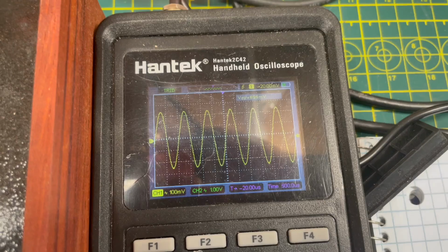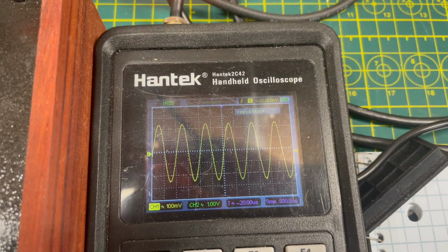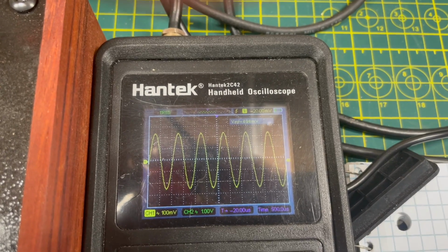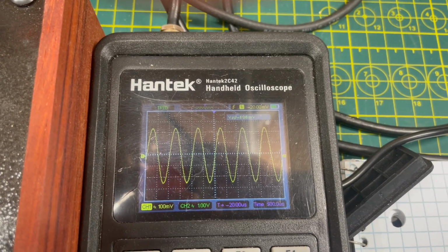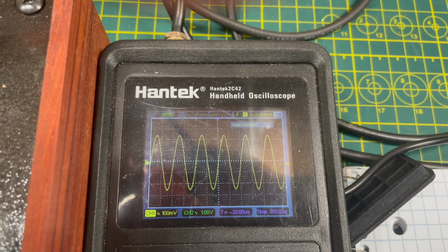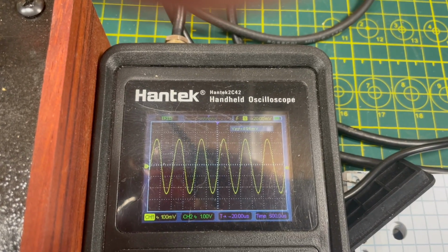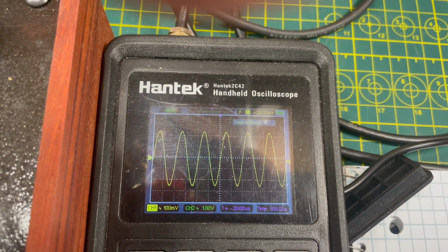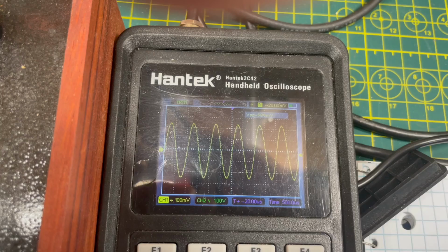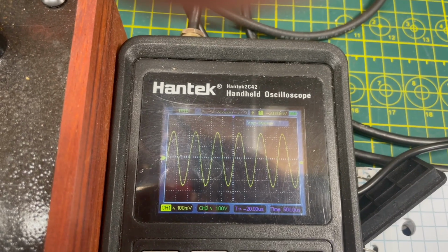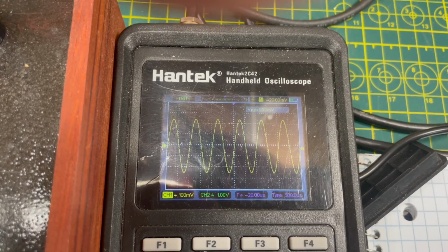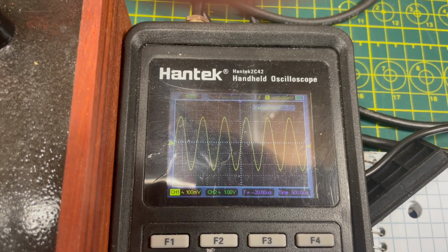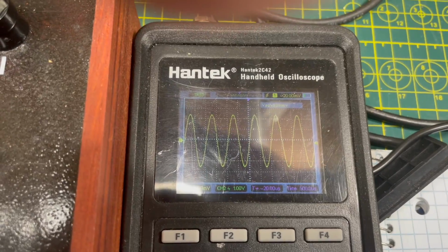And over here on channel B, we have the output of this scope, and we can see that peak to peak it's reading 500 millivolts. So what we're going to do is check the frequency response of this transformer by adjusting the frequency, and when that voltage goes down to 0.7 of 500 millivolts, which is about 350 millivolts, that's the 3 dB bandwidth minimum of the pass frequency. So we're going to go ahead and do that.